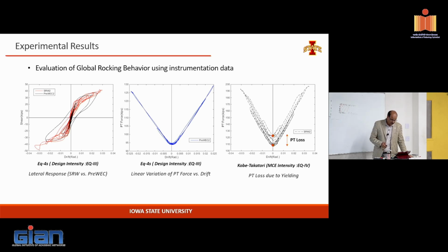So this is something I want you to understand: if you cause inelasticity, we did experience in some cases, then your post-tensioning stress actually comes down. So it went up here, yielded the steel, came down here. So we are now here, implying that we lost quite a bit of post-tensioning.